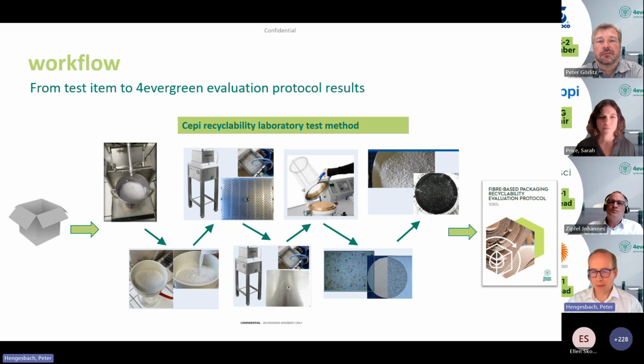Then you take the pulp after this stage and remove coarse contaminants or not properly repulped materials via a coarse screening stage. The amount of material that can't be recovered is measured and quantified. This is followed by a fine screening stage, which gives you some indication whether there are flakes or fiber bundles that were not repulped properly, or fragments of barriers, for example.